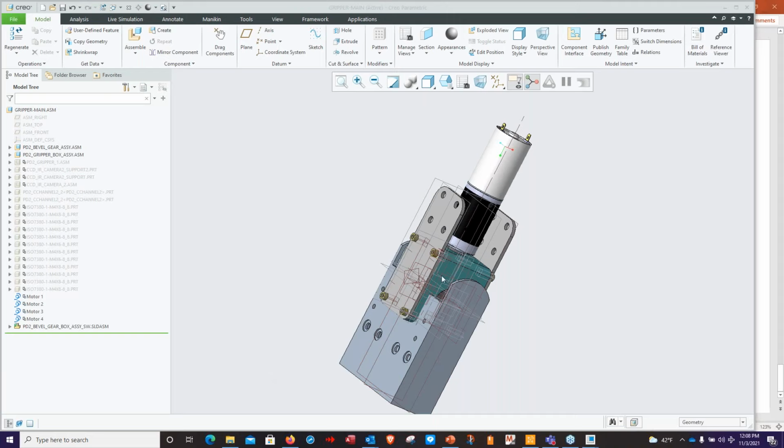Yeah, we're not modifying the Solidworks file itself. We're using that for references. You can add in Creo, if you're comfortable working in Creo, you can do some flex modeling, and you can make changes to a Solidworks part and reflect that back. But it doesn't physically make the changes. That is just more for reference. So you would have to then go back in and properly modify the Solidworks if that is going to be your driving CAD file.